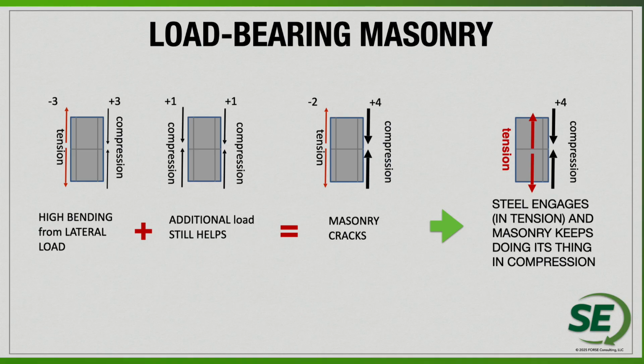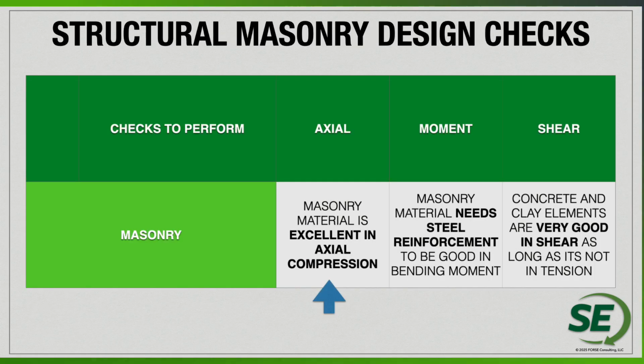We know that adding in the reinforcement is going to create internal tensile forces, because the masonry is going to crack. We're going to lose that tensile stress at the far edge. We know that the reinforcement internal to the wall is then going to start to develop some internal forces to create that internal force couple.